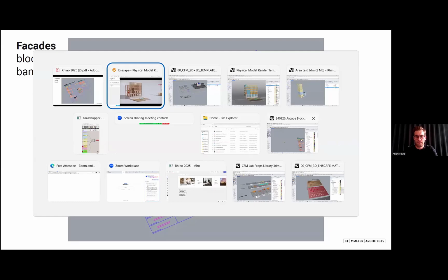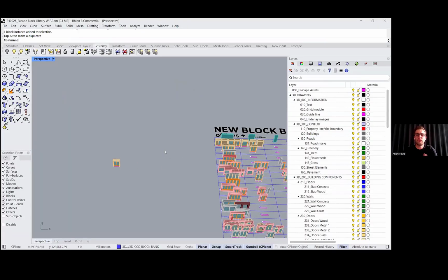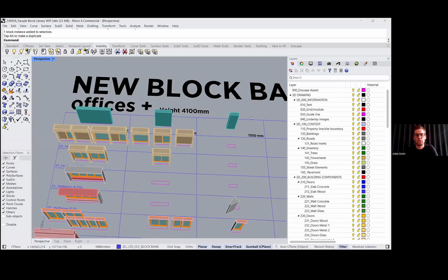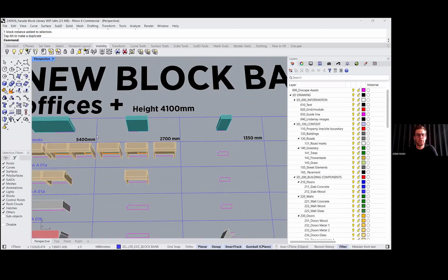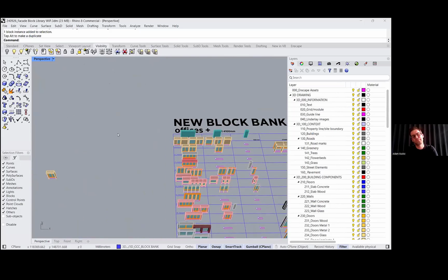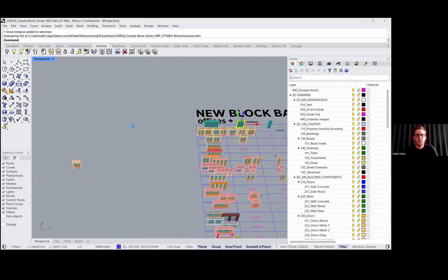And of course, your building and the facade modules will come in different sizes, but there are quite a few that we see consistently throughout our work. And the main modules that we are working with are 1.35, 2.7, and 5.4 meters. That's usually the ones that are, well, the most popular. So I'm just going to quickly show you our very simple facade workflow here.